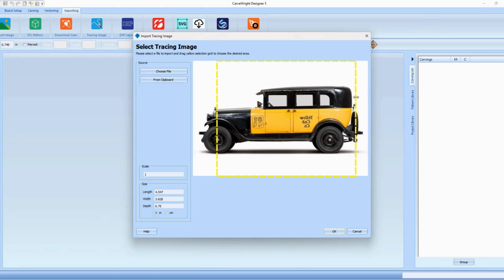In this case, this is something which I'm actually going to be modeling to a specific scale. So we can pull a little trick here, because I looked up what the wheelbase was on this original car, and the scale I'm using is 3/4 of an inch to a foot. So my length on the wheelbase should be 7.8125, and if I go ahead and enter that on the length here and hit enter, you'll see that a